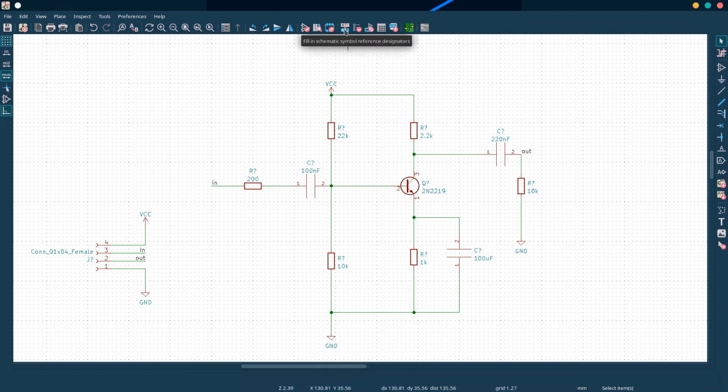Quick question. Were you saying something earlier about these just being labels that don't actually apply to anything? Yeah, I was a bit confused, because how does KiCad know how to interpret 100 nF as a 100 nanofarad capacitor? It doesn't. That's just the name you see on the schematic. Basically you pick a footprint, which is the physical shape of the component on the PCB itself. Then when you buy components, you refer to this: the component has to have this shape and be that value, and then it fits on this board.